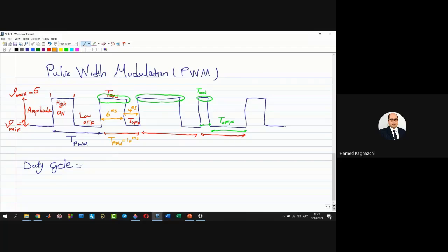Now, how can I calculate the duty cycle? I can say that T on divided by T PWM times 100.